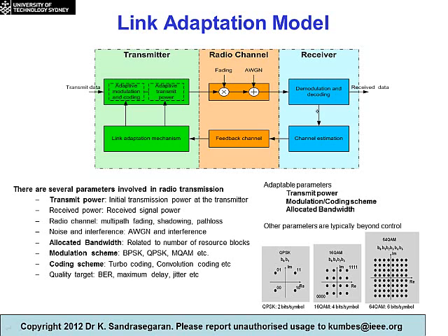The receiver demodulates and decodes the signal. It estimates the channel, and it sends the CQI on the feedback channel, and the CQI is used to adapt the modulation and coding scheme. In the case of LTE, you only change the modulation and coding scheme. You could also use this model for 3G, because in the 3G case we would change the transmit power.